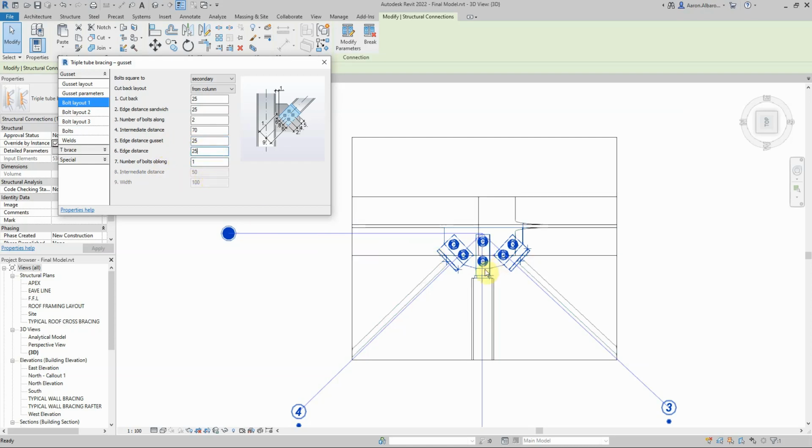That's it. So now the edge distance in the second direction is shown here to be 25. I need to increase it to be 35, which is, as we agreed, roughly twice. That will make it 75. Look at that. So that will make it wide enough. Okay, so you can make it if you'd like 40 or 37.5 if you want exactly.